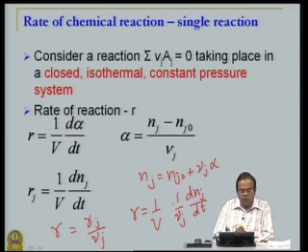What is the difference between R and Rj? Unit wise they are the same, but Rj is the rate of change of species j and R is the rate of the reaction of this particular reaction. So, Rj is for the species, R is for the reaction, and these of course are related, that is Rj by nu j is equal to R.